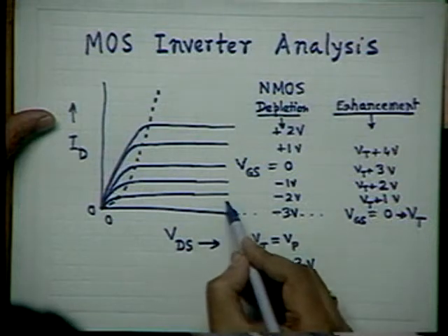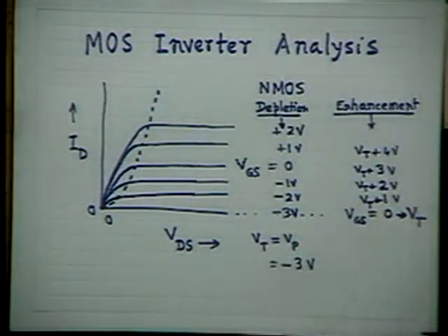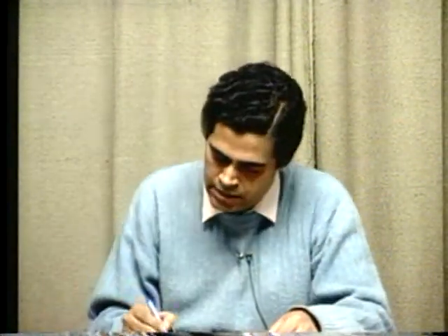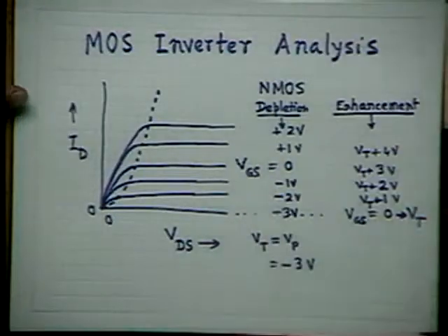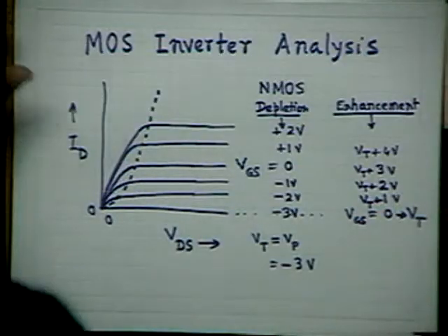Above a certain VDS, as you remember, the curves go up quickly, and that is what is called the breakdown in the MOSFET. That happens when the drain substrate junction breaks down. Then you remember the curves all go up. But below that, the curves are almost horizontal, and that is why this region of the characteristics is called saturation.